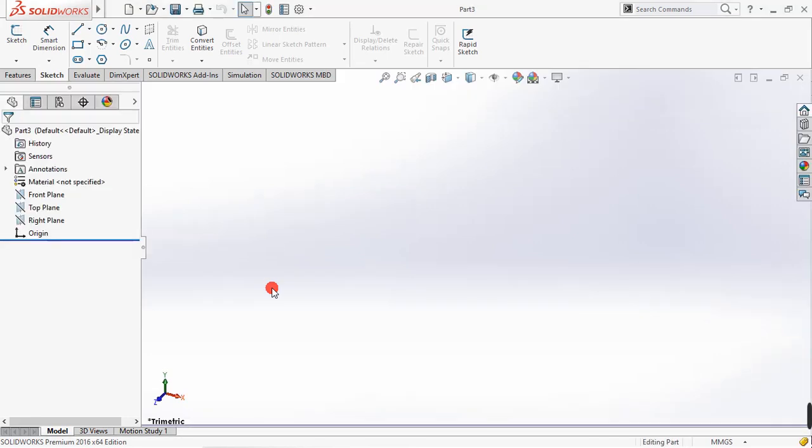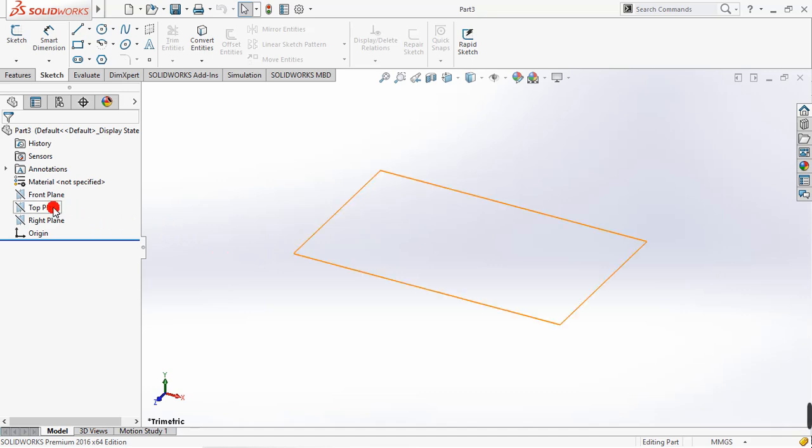For our compression test, we have two parts. The first one is the die, and the second one is the specimen. The die is the one that exerts compressive force to our specimen, and our specimen is the one that receives the compressive force. And of course, as we apply a compressive force, the middle part of our specimen will create a bulge due to the compressive stress.